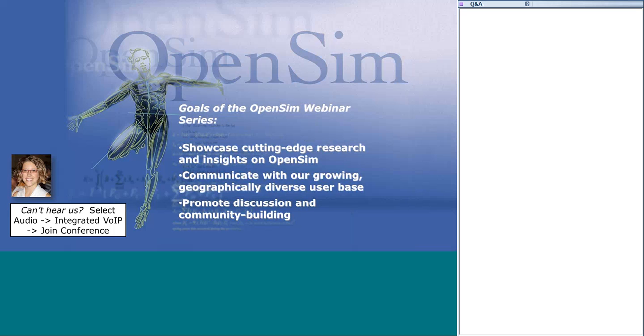So first, let me tell you a little bit about OpenSim. It's a freely available software application for visualizing musculoskeletal structures and simulating movements of humans and animals. The application includes tools for general purpose inverse dynamics, optimization to estimate muscle and joint forces, methods to create simulations for motion capture, and then tools to analyze and visualize the results of your simulations.